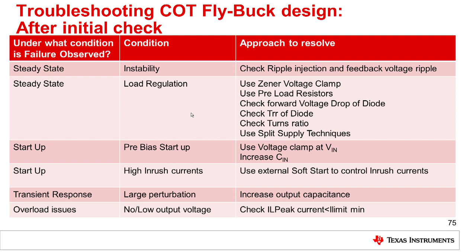And typically what that means is that we've somehow miscalculated how much peak current we need for the application, and the current limit on the regulator is limiting how much current we can get out. So we may have to choose a different regulator, or perhaps choose a different inductor to get different peak currents.